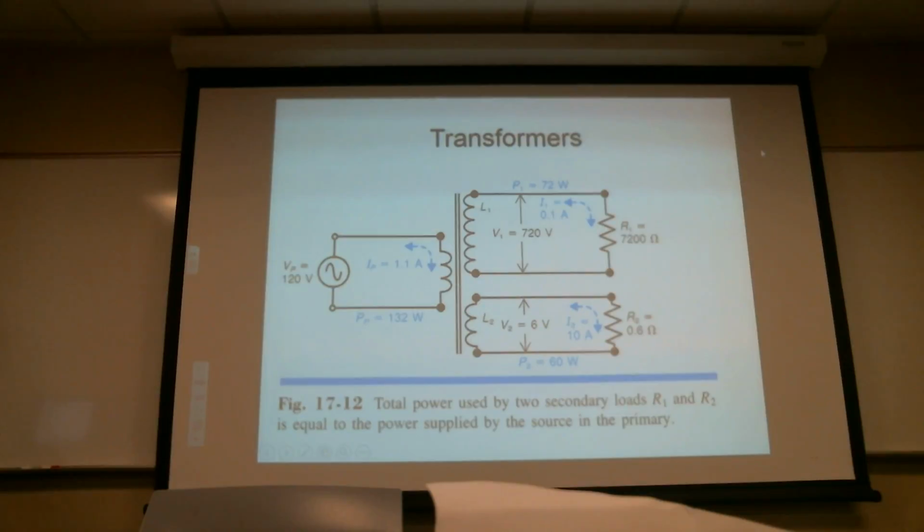Now, more sophisticated digital components, what they do is they'll use a transistor of some kind to completely load shed it. When it's off, they shut it down to where all it's doing is using a few milliamps to monitor whether things have been turned on or off. And if they're in the off state, they load shed completely, and the circuit sees this as one of those wires disconnected.